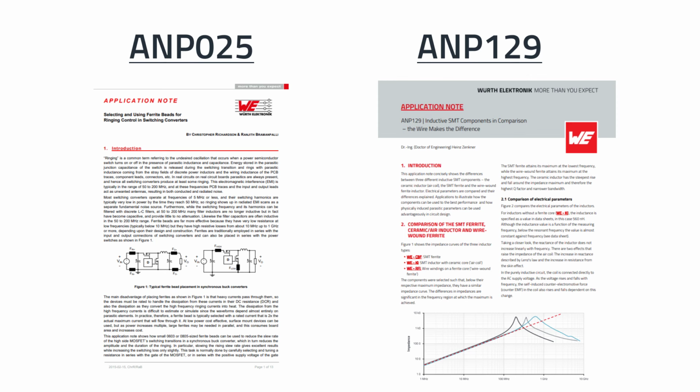The ohmic or resistive components of the impedance of the surface mount ferrite should be as low as possible, up to the fifth harmonic of the signal frequency. And the impedance at this frequency should be less than 1/10 of the system impedance to avoid affecting the useful signal. So in our example, the fifth harmonic is at 25 megahertz, as the signal frequency is a 5 megahertz square wave. Since the system impedance in this example is 90 ohms, the impedance at 25 megahertz should be at most about 1/10, so no more than 9 ohms.